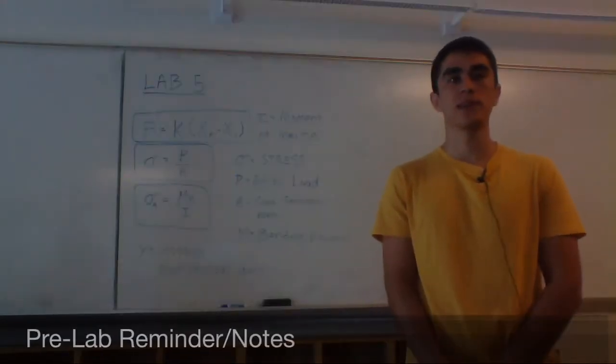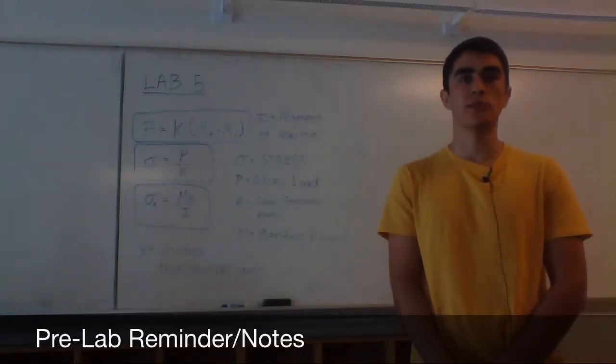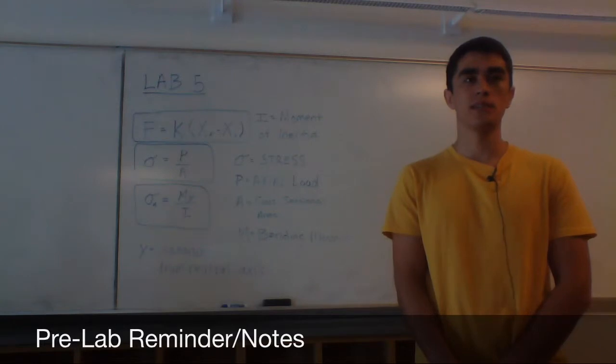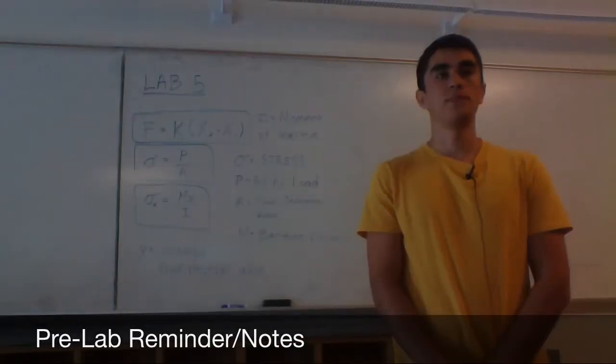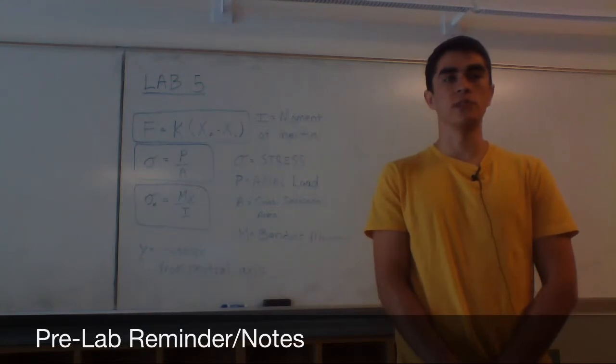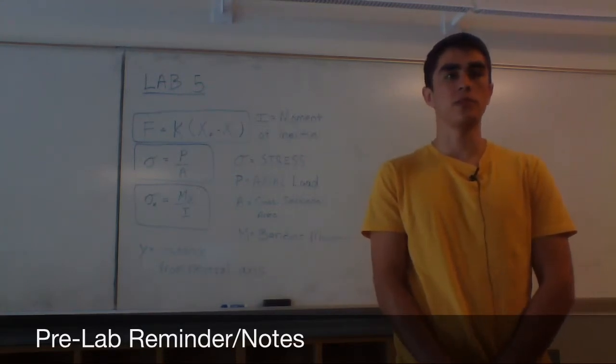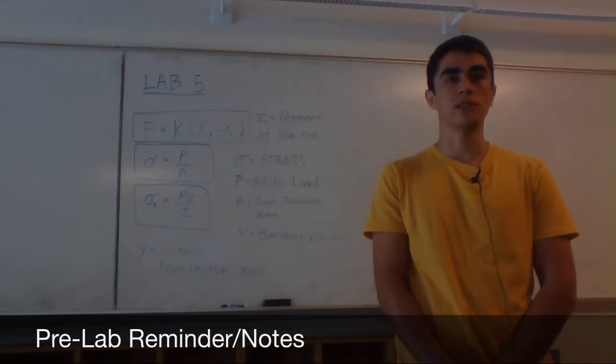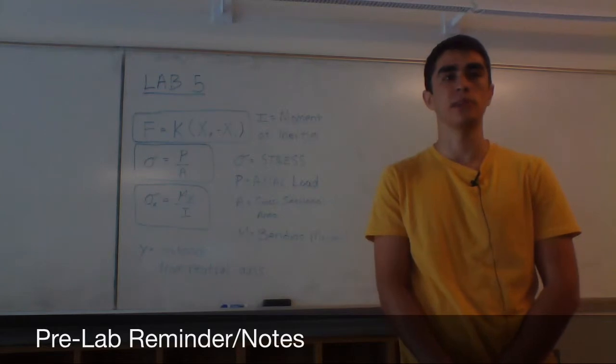For your pre-lab, several calculations should be performed before the lab exercise is performed. See the pre-lab worksheet and determine the tension and bending values for the specimen. Note that all force measurements will be in units of pounds. Strain measurements are dimensionless but will be recorded as microinches per inch. All stresses are in pounds per square inch, and the modulus of elasticity also has units of pounds per square inch.